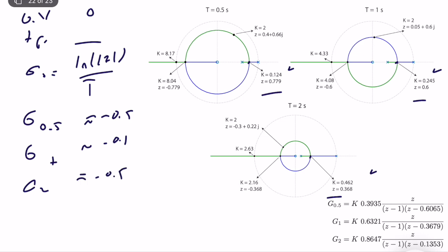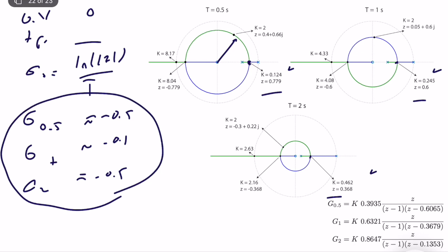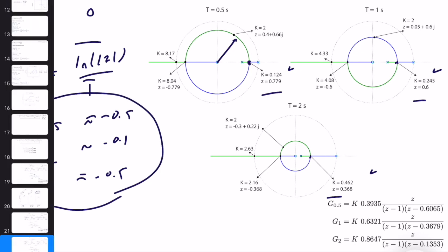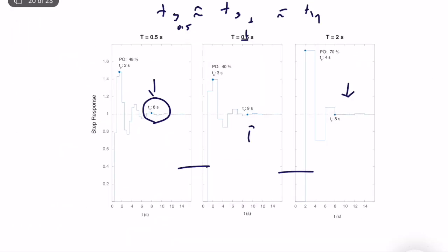It's obvious because, as you can see, this is a perfect radius. The magnitude here, the radial magnitude, is same with the magnitude k is equal to 2. Since I'm picking the same locations in both cases, of course I should expect the same settling time with k is equal to 2 value. So settling time performances should be similar to this, such that in actual time, settling time is equal to approximately 9 seconds.